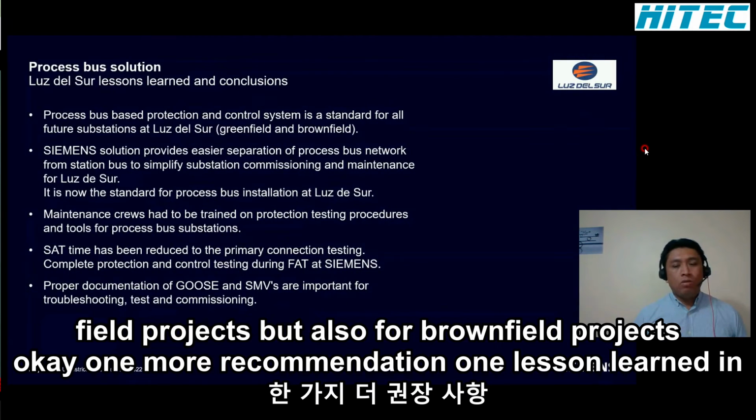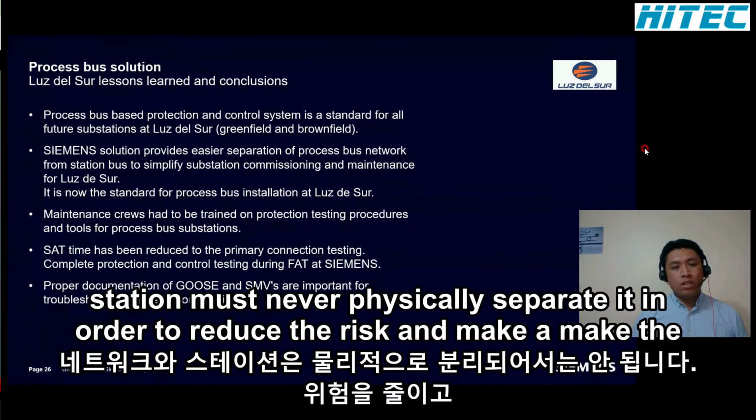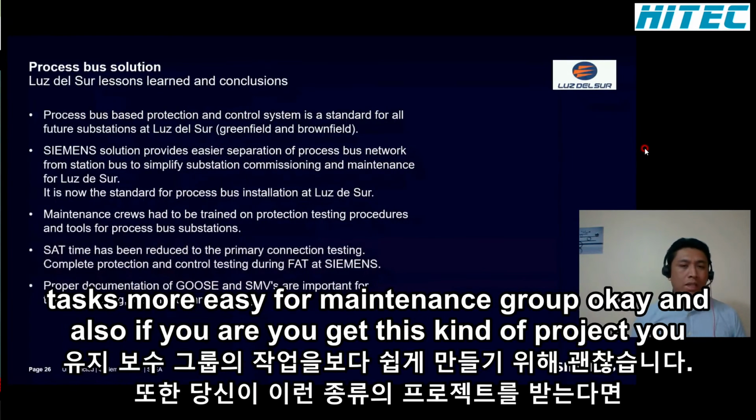One recommendation or lesson learned, if you are starting on this kind of solution, is that it is easier to implement the process bus network and station bus network physically separated, in order to reduce risks and make the task easier for the maintenance group.